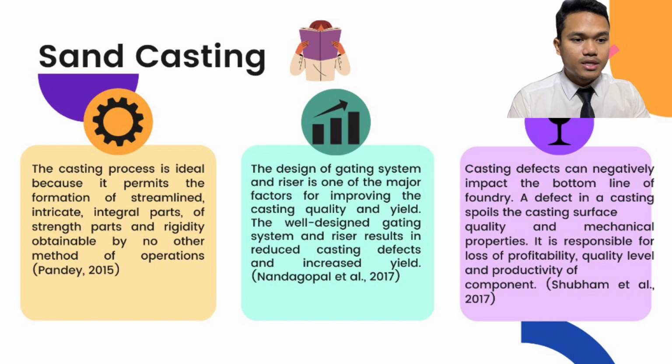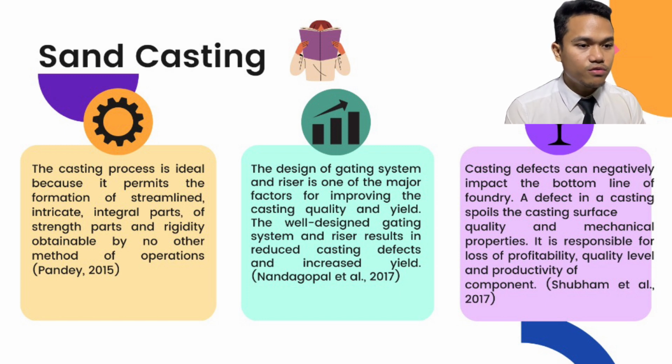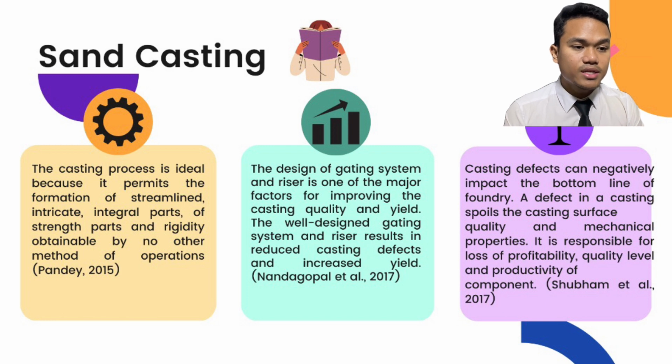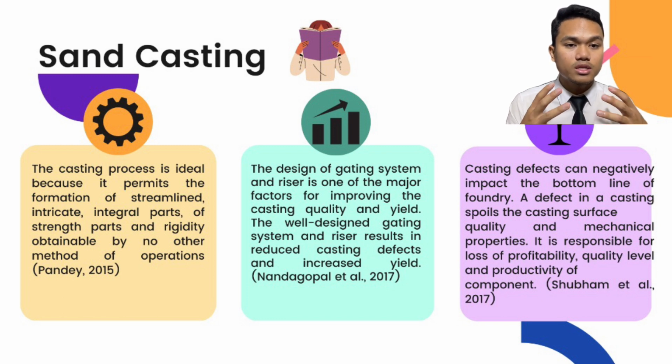Lal Narayan Pandey said that the casting process is ideal because it permits the formation of streamlined, intricate, integral parts, strength parts, and rigidity obtainable by no other methods of operations, which means that the product can only be produced by the sand casting process. Next, Nanda Gopal et al. said that the design of the gating system and riser is one of the major factors for improving the casting quality and yield. A well-designed gating system and riser results in reduced casting defects and increased yield, which means that the gating system needs to be designed properly.